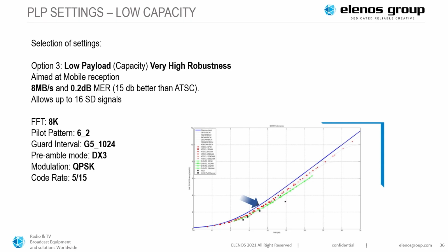And this signal would be in the signal-to-noise ratio of about 8 dBs. So, as an example, ATSC1 is 15 dBs. You need at least 15 dBs signal-to-noise ratio to receive an ATSC1 signal. This would be more than twice the noise level and still be received by a standard receiver. And that's basically it. You would choose that and then make slight modifications on all of these settings, slowly moving up the graph or down the graph, depending on who your customers are.